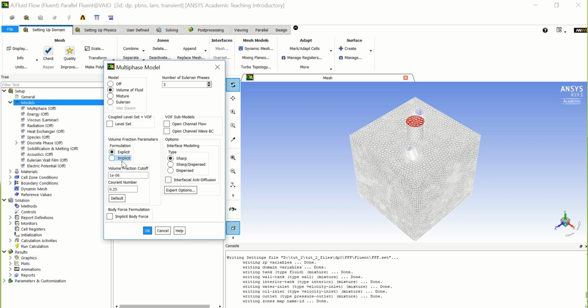Now this can be used for large time steps, and it allows the reduction of CPU time, and it is unconditionally stable. It is always stable, which is not the case for the explicit scheme. In order for the explicit scheme to be stable, its condition is to have small time steps, and I will show you the range of the time step you could use in this example.